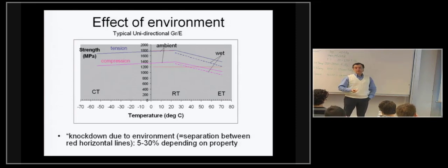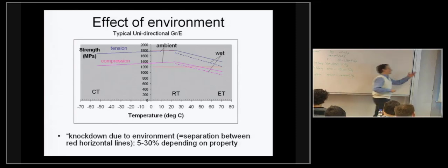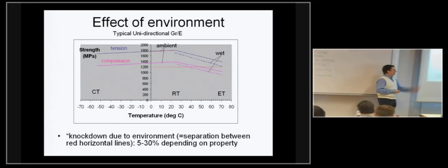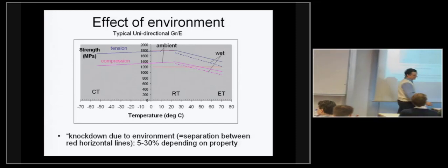Or if you want to live with that, but nobody does it to my knowledge, you have to use extra reduction factors for material operating too close to its glass transition temperature, and that's for long-term performance in terms of fatigue loading, it's a bad idea because you will really be degrading the structure itself. So, for example, room temperature cure materials, you have to be careful if you intend to use them in very hot environments.